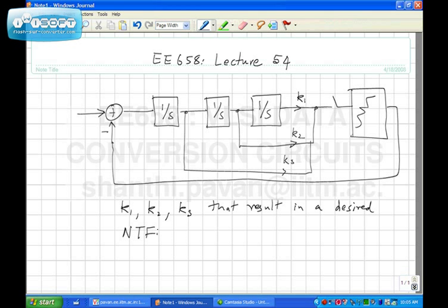And even though the input signal is varying with a very low frequency, that doesn't matter because the flash is sampling at every clock edge, right? And you know that when you have sharp edges in a simulator, simulation time will increase because at the edges the derivatives are very high. So the simulator will go very slowly to make sure that it is giving you the correct answer. Or at least you're supposed to set the simulation tolerances so that is true. Does it make sense? So the simulation will take a long time. There's no running away from it.